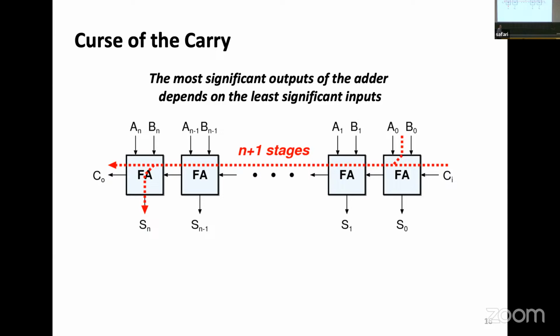And after a while, this carry propagation created a massive mess. It propagates back and forth, and everybody says, oh no, I just finished. Okay, let me do it. Here, take another carry. Are you kidding me? Okay, here, take the carry. And then after quite a long while, if this is a 128-bit adder, after 128 time units, this guy will finally say, okay, you know what? The result is 0.